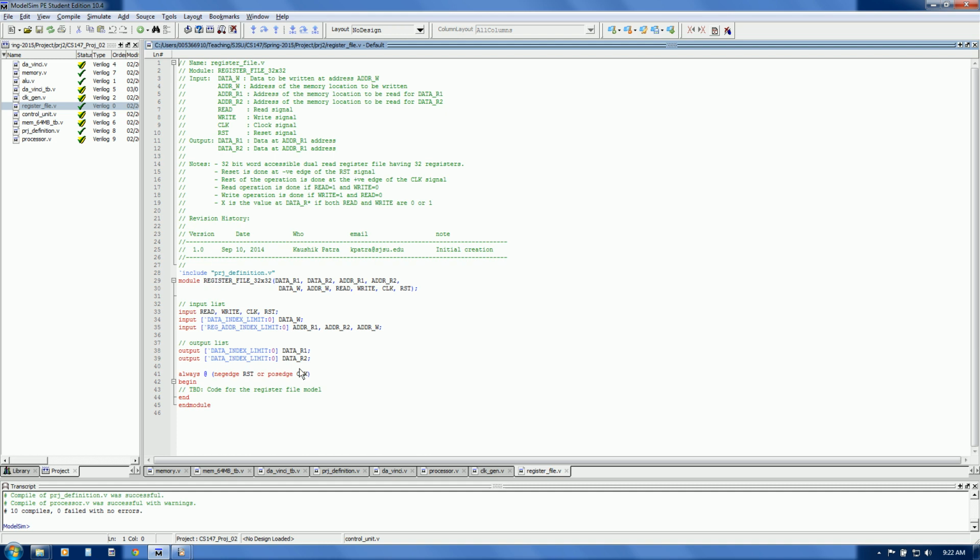R1, R2. So what you need to do is basically, for each reset and negative clock, do a similar thing to what the memory does. You also need to possibly add storage, like the memory. Okay, the 2-dimensional storage, in this case 32 bits by 32 lines, right? So for that, add storage and add a data return register, just like the memory, right?